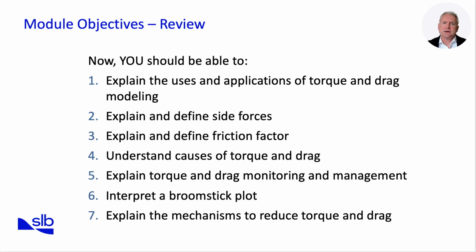We then examined stiffness in drill collars, defining it as Young's modulus multiplied by the moment of inertia, and demonstrated how the outside diameter has the strongest influence on bending resistance. Finally, we reviewed the Dawson-Pasley buckling criteria, which predict the onset of sinusoidal buckling and the transition into helical buckling at higher compressive loads. Together, these concepts provide a framework for anticipating and controlling drill string mechanical behavior in deviated wells. In the next submodule, we will look to explain and define friction factors and understand the causes of torque and drag.